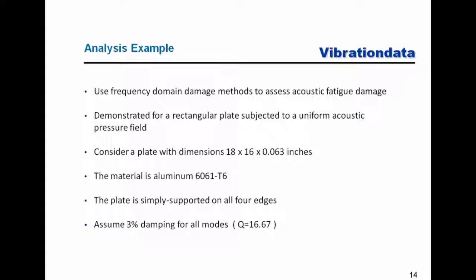Now for this case, we're going to have a rectangular plate, and it's going to be subjected to a uniform acoustic pressure field. So this is going to be a very simplified example. In many cases, acoustic pressure fields are more complex. There could be spatial variation from one point to another. There can be variation in phase angle and coherence and correlation and all those different things. And those are more advanced acoustic topics, and we will probably get to those in some future webinar.